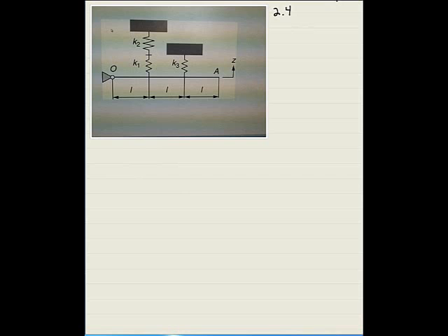If you stop the beam from moving, then there's still a motion, which is the junction between K1 and K2. So what I'll do is define a variable for that one that goes like this. I'll measure it off of static equilibrium. When I say up is positive, we're going to call that variable y.